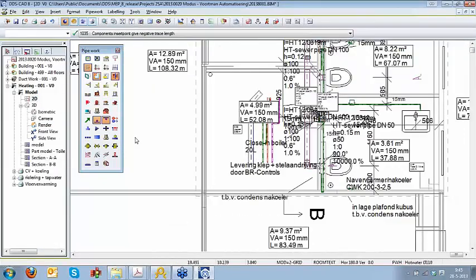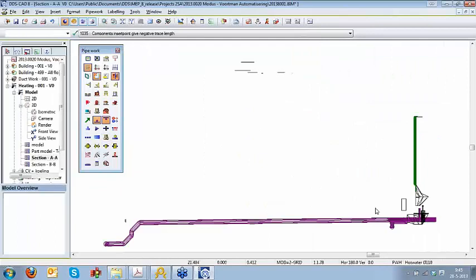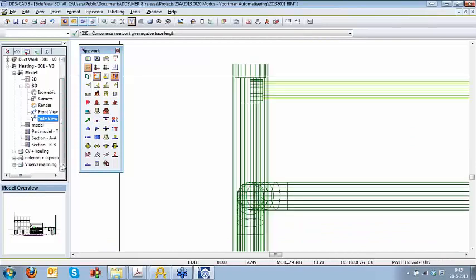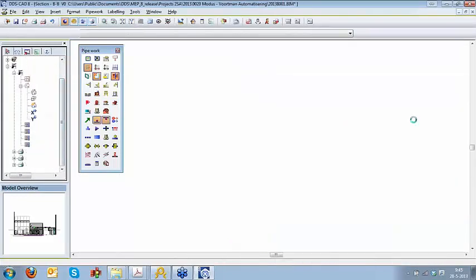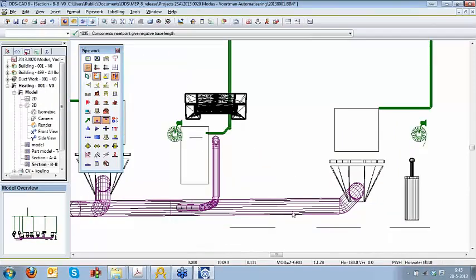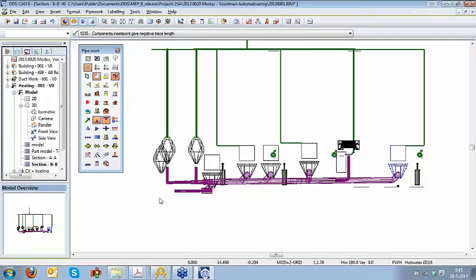We saw that from our section view, we applied the connection from the sewer system with the slope to the main branch. We created some connections to sanitary elements. So we connected the toilet with an upward slope at the end point of the main branch.